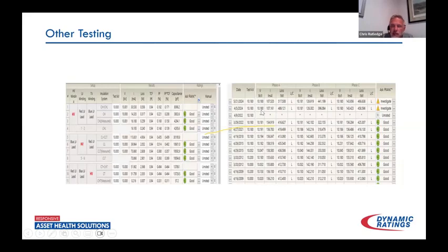However, in the last two tests done this year, we see that in A phase, we've gone from 156 down to 107.1, 126 on C phase, and 143. So now we've got sort of a stair step type excitation current test.